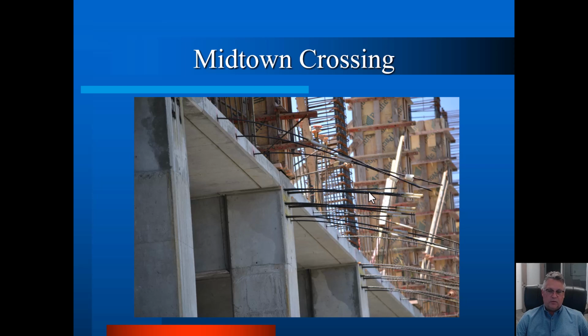Dramatically different than reinforced concrete, which, if it's not post-tensioned, it has to sit formed for at least 21 days, many times 28 days, to get rigid enough, to get strong enough, and to get stiff enough. Post-tensioning effectively eliminates the need to do that. Once the tendons are stressed, the system will stand up on its own. And it's a tremendous speed benefit for post-tension concrete relative to reinforced concrete.